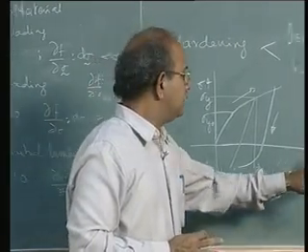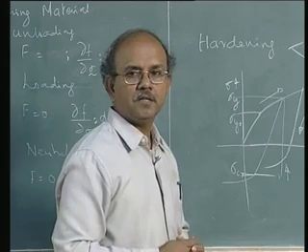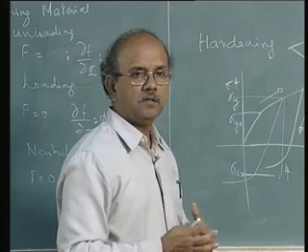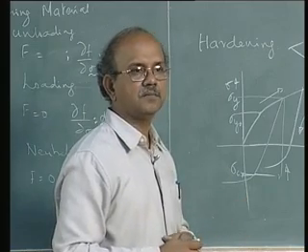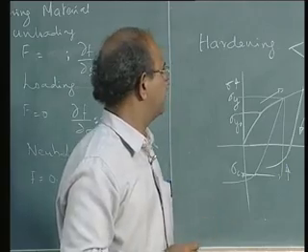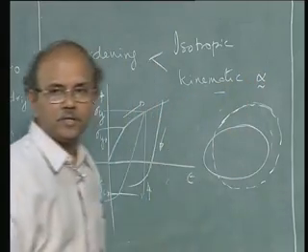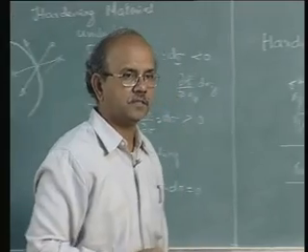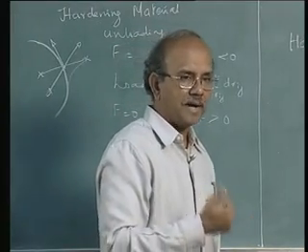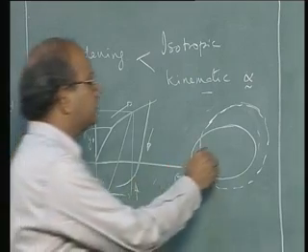So, this kind of motion for the yield surface is brought about by certain tensors which are called back stress. So, kinematic hardening has other tensor variables apart from stress, these are called back stress, okay, which pulls the point.